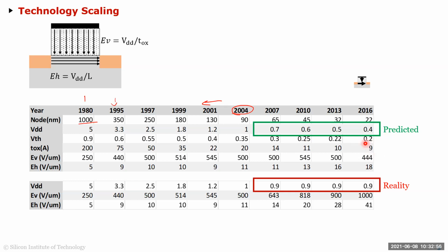Plus, if you went for this low a threshold voltage, you'll never be able to switch it off, primarily to do with process. You just won't be able to dope those areas to such a precise level in nanometer dimensions, such that when you take your VGS to zero, IDS is going to be zero. And that's what has kept these voltages constant, because they wanted higher VT.